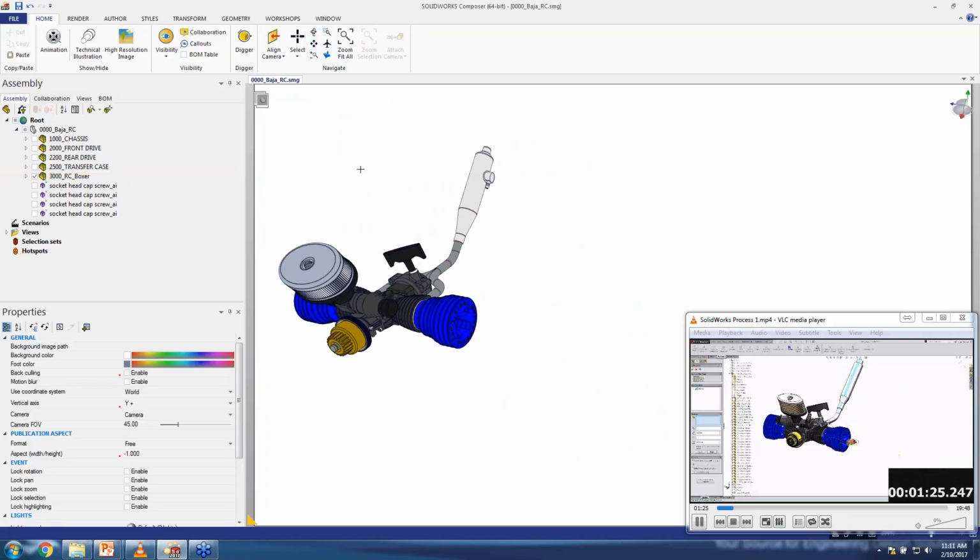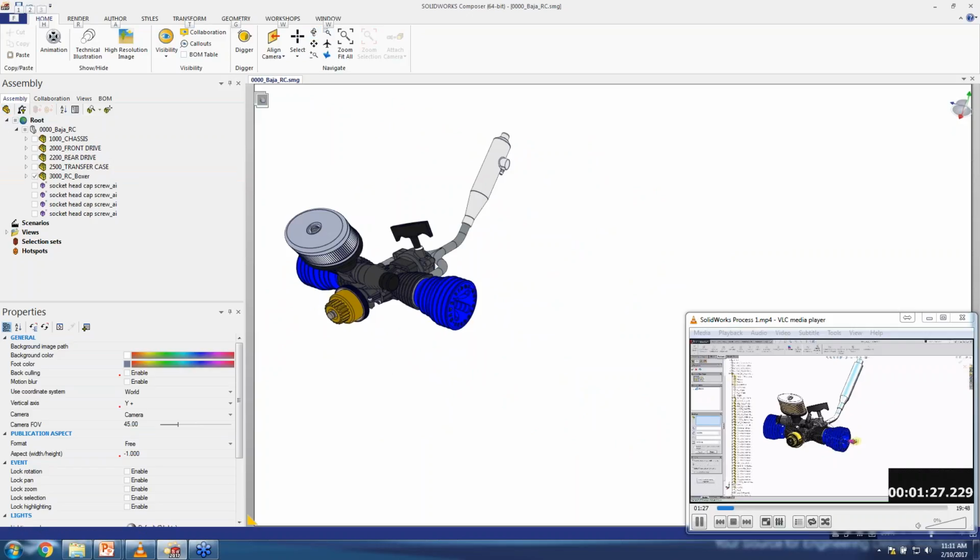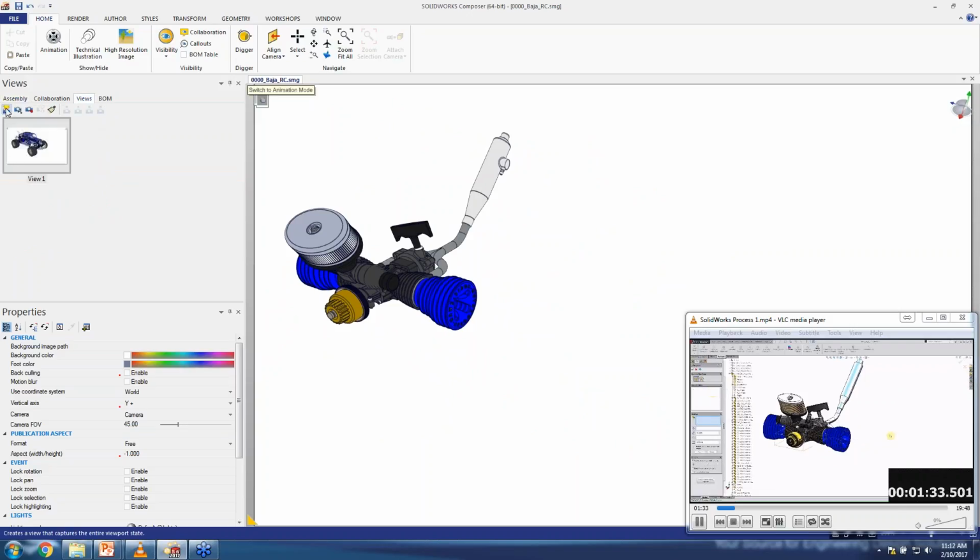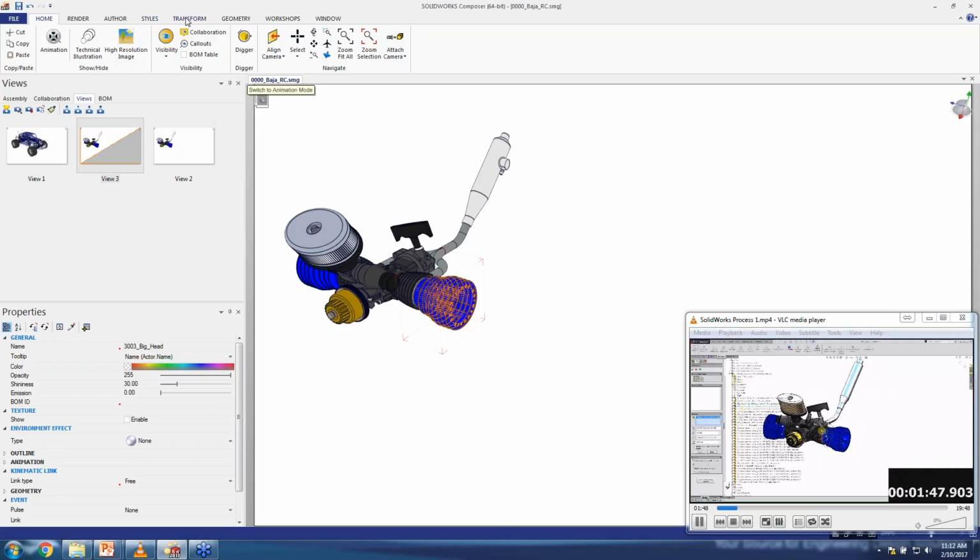And let's rotate this a little bit just so I can get a good angle for my exploded view, which is developing right now in SOLIDWORKS there. So I'm going to go ahead and create a view. I'm also going to create what's a camera view, and I'll explain why I have that. Basically, that controls my camera angle, and I can always get back to it, and I don't have to worry about anything messing up here. So let's go ahead and start exploding this apart.